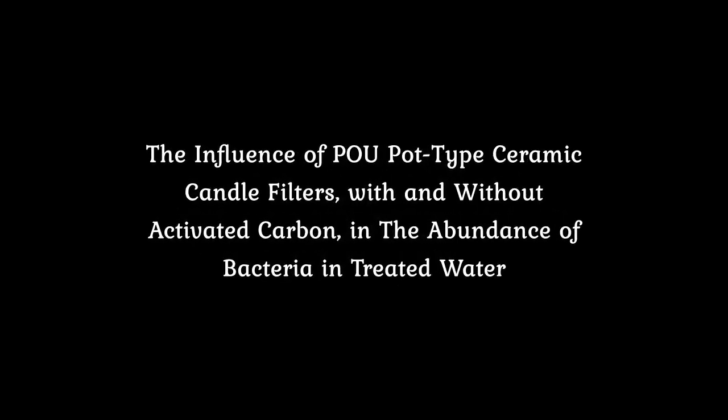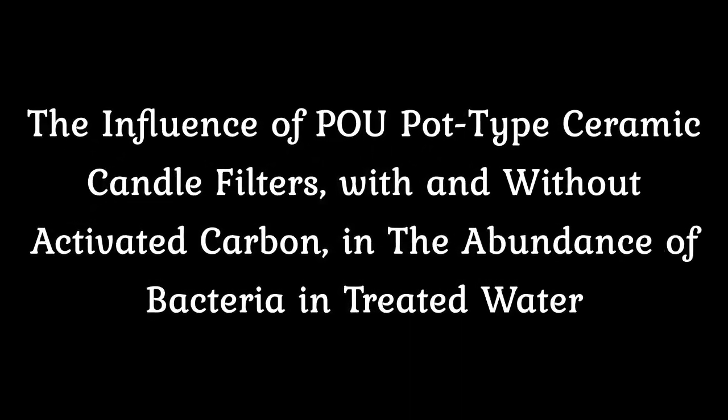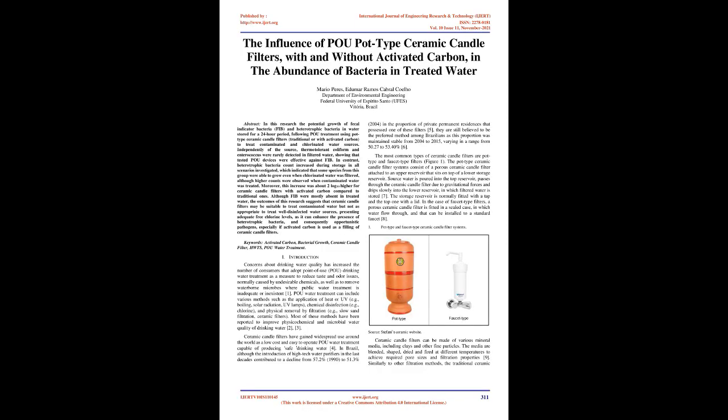The influence of pot-type ceramic candle filters, with and without activated carbon, on the abundance of bacteria in treated water. Abstract: in this research the potential growth of fecal indicator bacteria, FIB, and heterotrophic bacteria in water stored for a 24-hour period, following POU treatment using pot-type ceramic candle filters, traditional or with activated carbon, to treat contaminated and chlorinated water sources was investigated. Independently of the source, thermotolerant coliform and enterococcus were rarely detected in filtered water, showing that tested POU devices were effective against FIB.